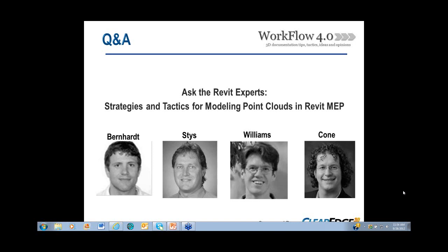Yeah, so this is Kyle here. I can add just a little bit of background. Sure. So, those are what we call the system family type for the pipes, and that's really just a native setting inside of the Revit project itself. Effectively, what the folks at EdgeWise are doing is running the pipe creation tools in the background, transparent to the Revit user. So just like you can set the pipe type when you create a pipe run yourself, you could do the same thing via the API. So ultimately, if it doesn't necessarily work this way now, it certainly could work this way in the future to present you a choice as to what pipe type you're looking for. And that's if you want to natively go straight to piping elements. But as Kevin mentioned, placeholders are effectively a generic system family type, and you can convert those into any system family type that would be available in the actual project. So it's really up to you, the user, to decide how you want to convert those placeholders.